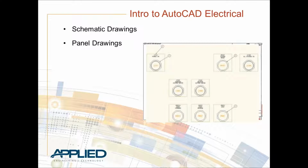Panel drawings. Panel drawings are basically your footprint for the components. So if we were laying out a cabinet, for example, if we had a Hoffman cabinet of a certain size, we could lay out the push buttons and various relays, DIN rail, etc., to make sure that when that set of drawings gets down to the production floor and somebody goes to assemble that cabinet, the components fit in that cabinet. The catalog data contains all of the physical dimensions for the components that you can utilize.